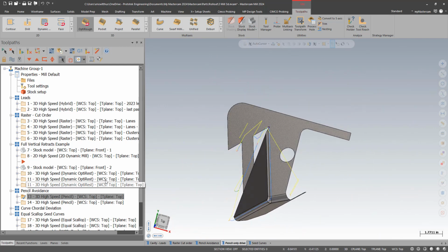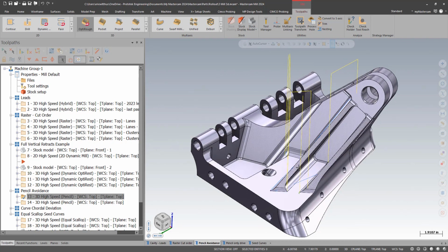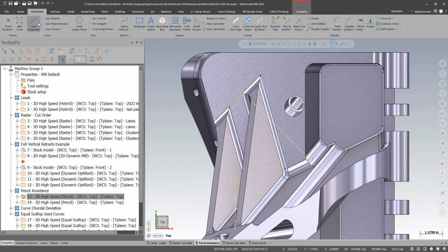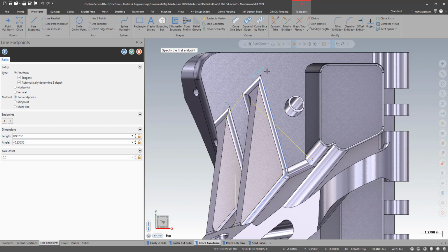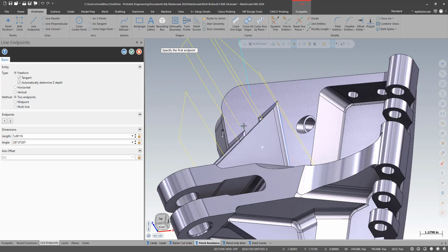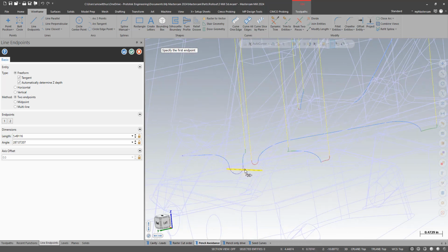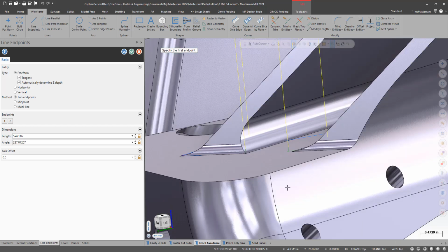So I learned pretty quick that you can't do that. My workaround is, I pick the whole part and then I look at where I have the cut I want. I can see where the blue lines are where I want, and I would draw in geometry around that. I keep going around encasing all that and then just pick that as containment. So I picked the whole model so it wouldn't gouge stuff. Right now it's gouging. If I turn this on, it's gouging down to the part, so I only picked those few faces. That's another important lesson, and one of the first lessons we teach in our surfacing class. If it's not selected, it's ignored. It can gouge it. It has to be part of the toolpath for it to be looked at.